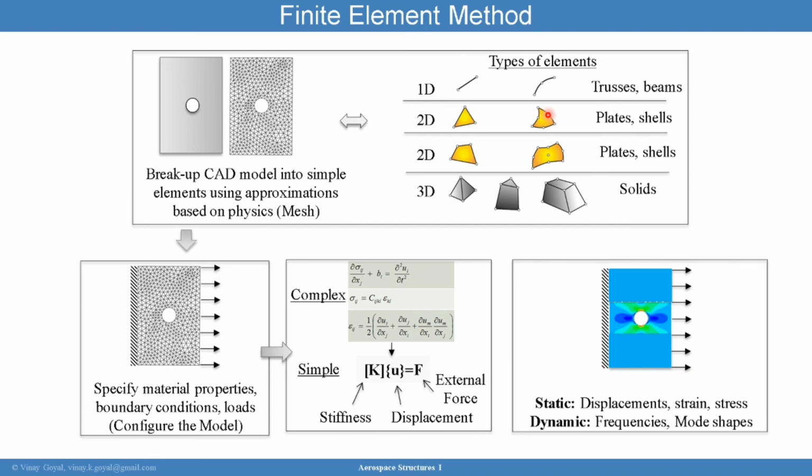And again, this is not a finite element modeling class, although we're going to do some finite element modeling. However, I am giving a top level view of what finite elements is really trying to do. And so we discretize a model into subdomains using triangular or quadrilateral elements. And then I take this model and apply loads and boundary conditions to the model, and I specify material properties.